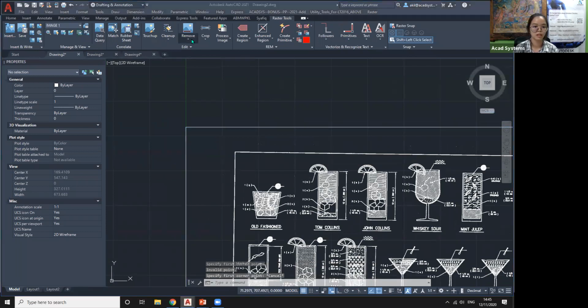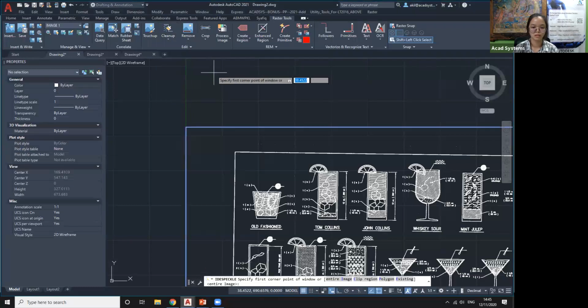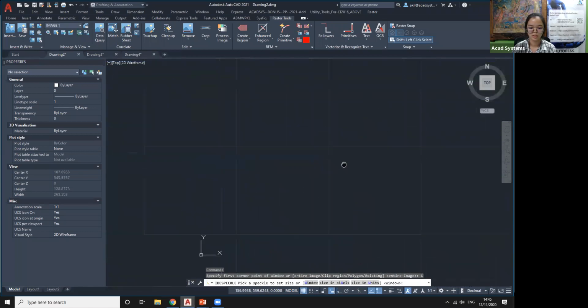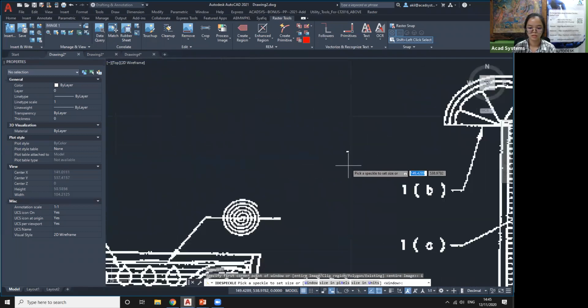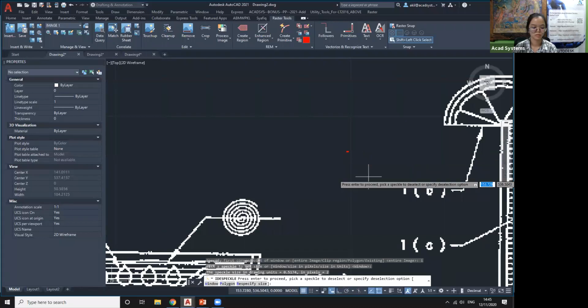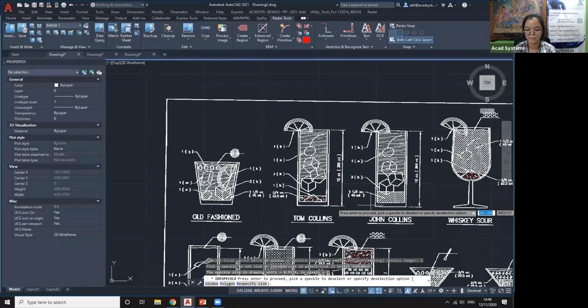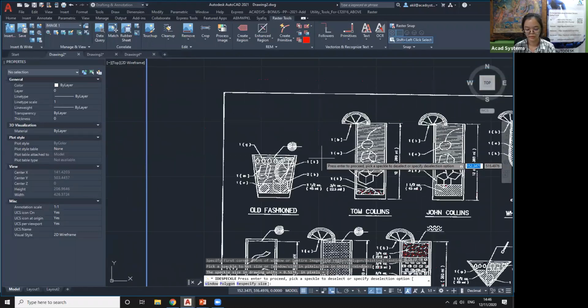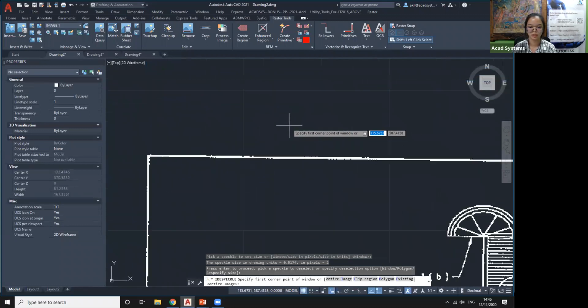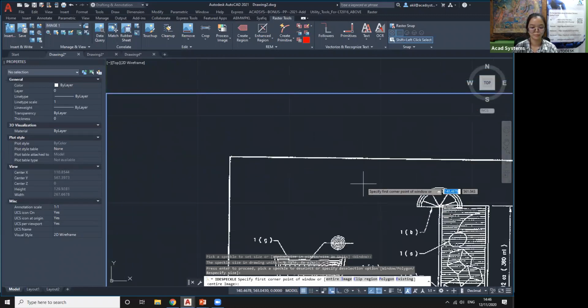Do again. Speckle, entire image. Speckle, okay. So when you are done, the similar size speckles that are found are highlighted in red and you are prompted to accept the selection set of what is about to be cleaned up. Now you can see it will become red color. So when you click enter, you can see the despeckles already being cleaned.